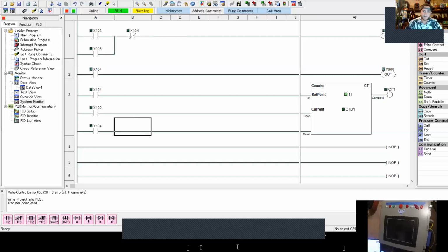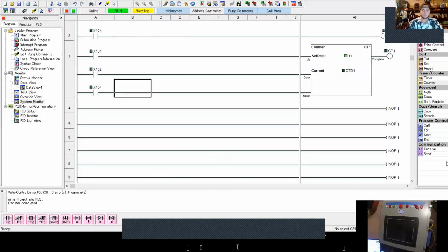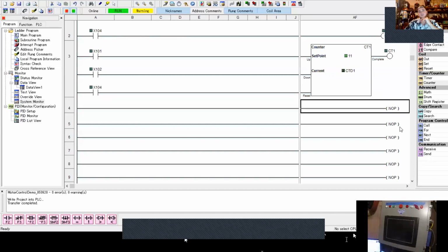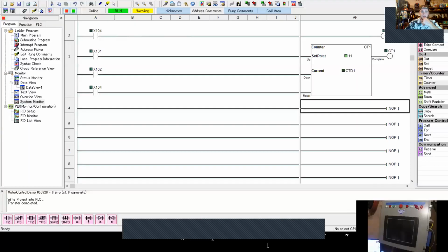Okay. So that's just something to be thinking about as you're programming in here, like why you're doing things that way. Okay, so the next thing we need to do on here is we need a way to write that counter value to our analog output, to the VFD. So if you look in your index for the PLC, that analog output, if you look at slot 4, channel 1, which is VFD speed 4 to 20 milliamps.